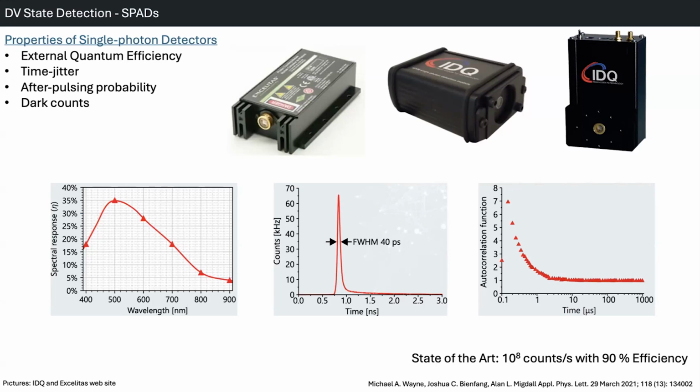All right. Second is the time jitter. So time jitter means you are detecting photons one by one, but what kind of time should you attach to these photons? The detection window or the detection jitter should be very small if you want to go to high photon count rates or fast gate operations, right?